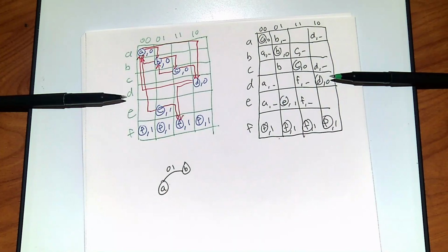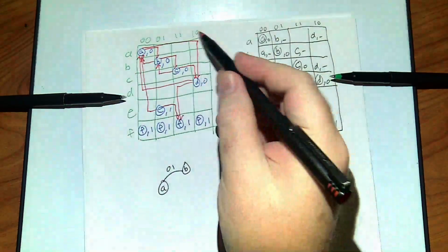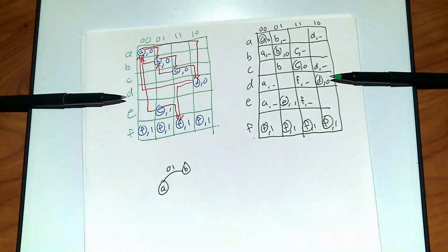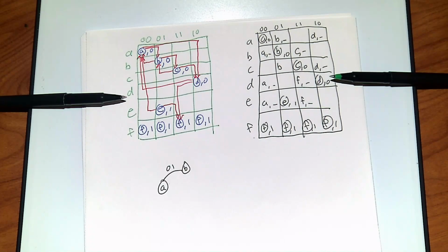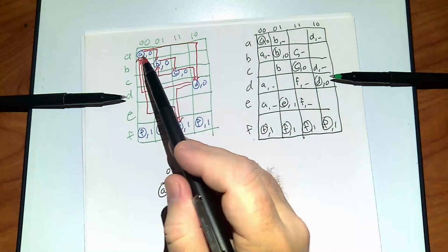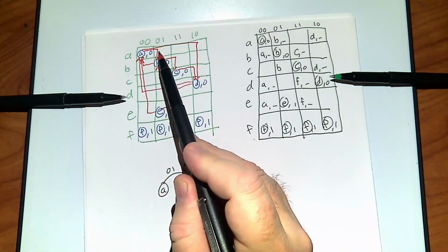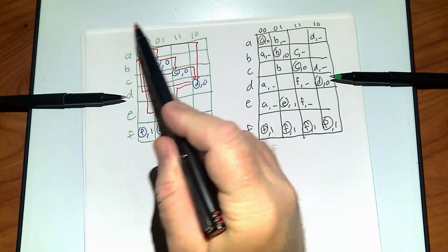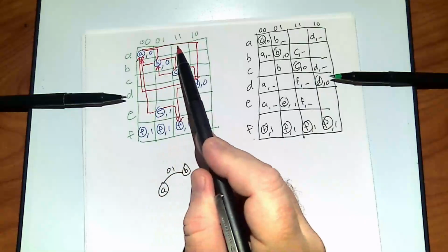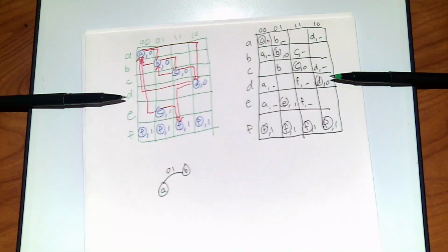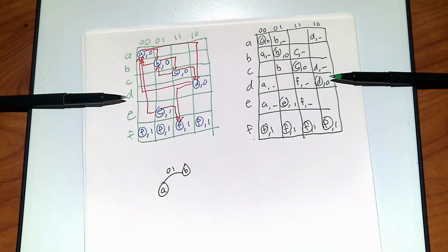If you notice in every one of these, I only did the one, and remember these wrap around, so 0, 0 is right next to 1, 0. It's like a piece of paper you can fold into a tube. So I can say, hey, look, there's no race to go to this square or to wrap around and go to this square. But from 0, 0 to 1, 1, that's a race condition, right? Inputs. And I don't like that. So I'm deliberately not touching those because I don't want to make them part of the requirements.